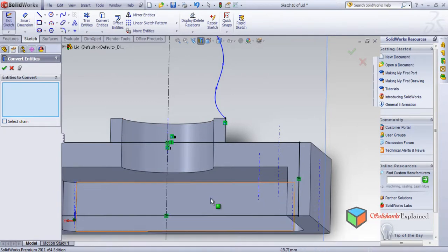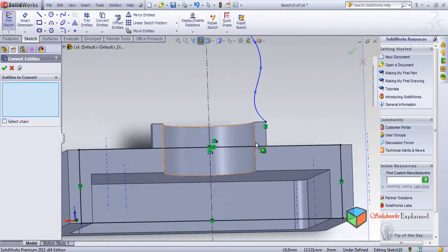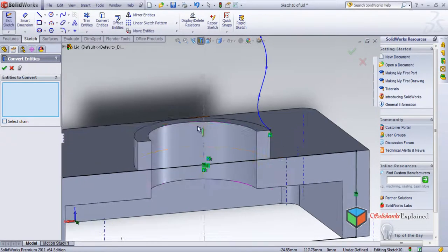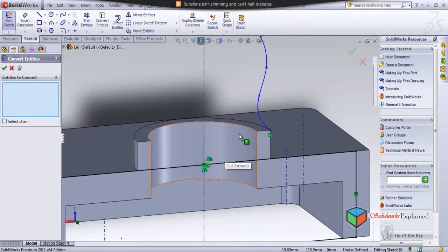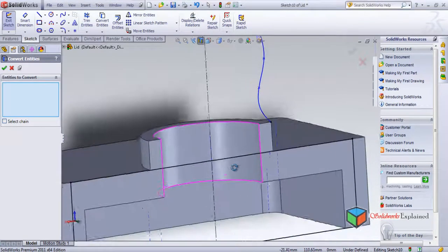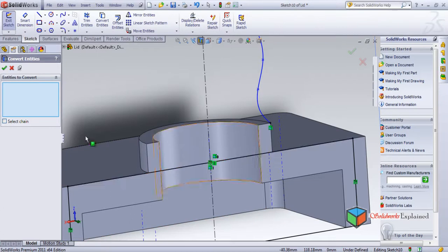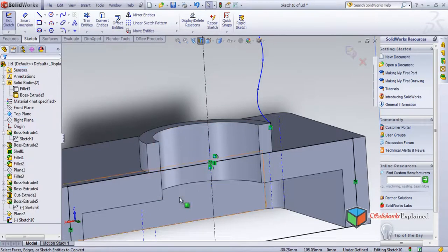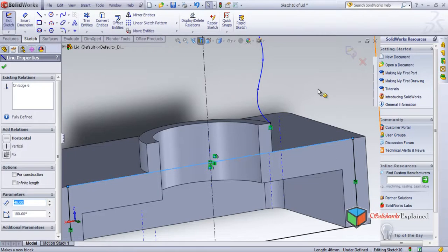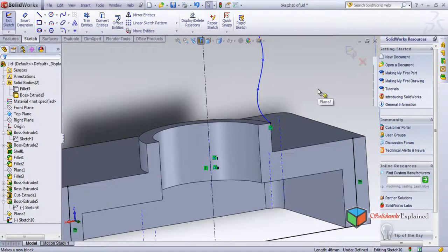That's the question. We don't require this thing, but sometimes you need to convert entities properly, because the part you are making should coincide, should fit into this neck of the bottle. If you don't convert to entities, then there will be assembly problems, and after the part goes into production, you will find some difficulties, or you need to finish the part and then make it okay. So this is the thing. Converting to entities is a good thing. So cross it. What we have done is we converted this, which you don't want. So select this and delete.